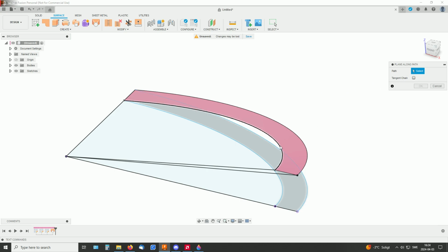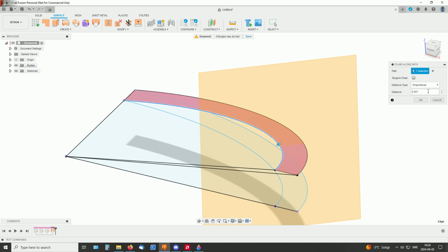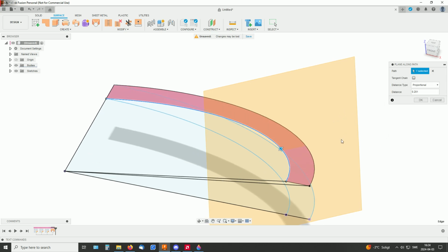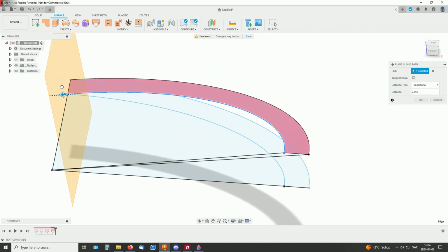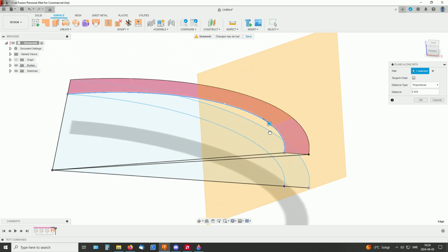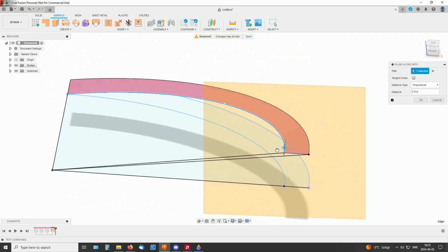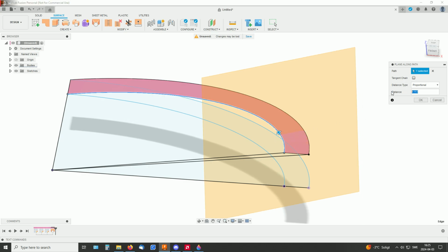Select path here, and if we want perhaps 10 sections, I choose 1/10 of this path. The whole path is 1, or very close to 1 there, and here it's 0. So at point 1 it should be 1/10 of the path.